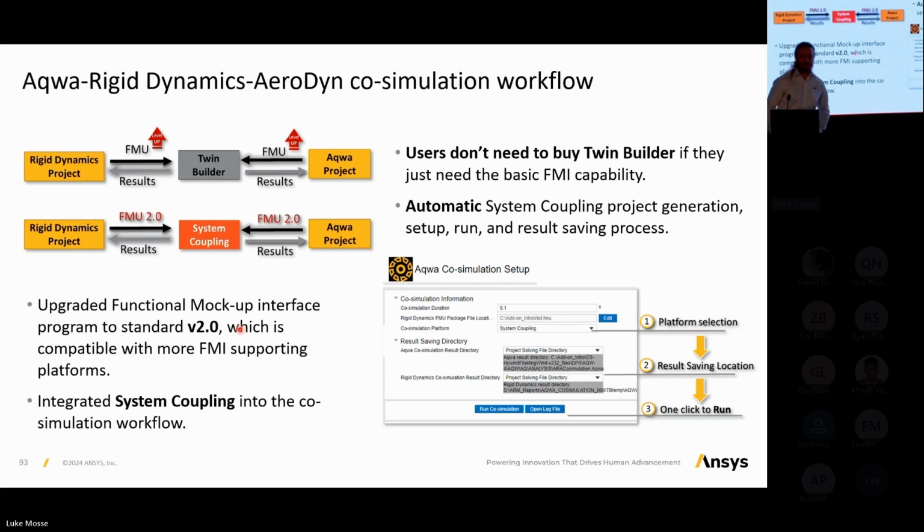And also, if we're doing something like a wind turbine on a floating structure, it's quite a complex simulation that involved some extra licensing and other stuff. That's been streamlined and made a bit cheaper as well. So we'd have to do, say, a rigid body dynamics analysis on the wind turbine itself. We would use AQWA for all the hydrodynamic loads, and then that would be fed into a Twin Builder to solve this analysis.